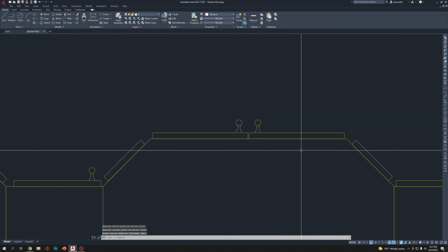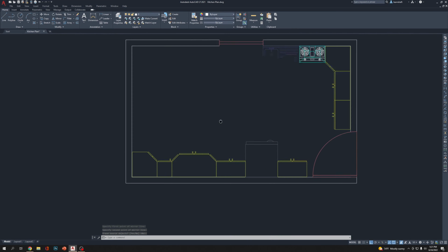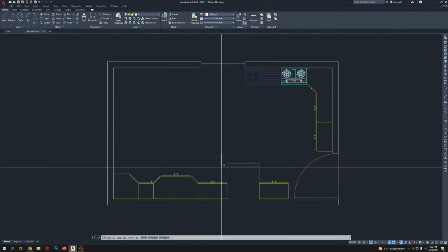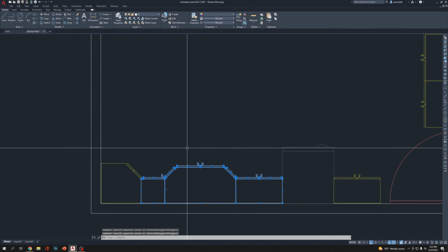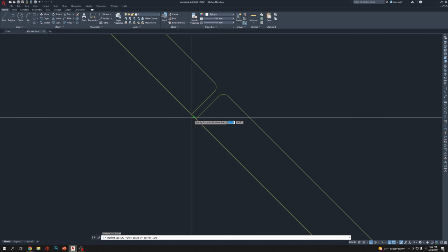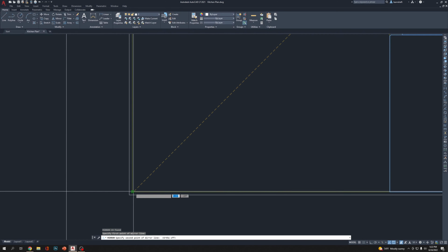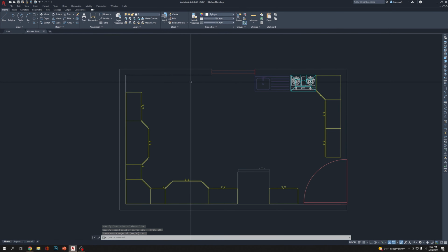I'm mirroring it to the other side, so this box is going to look like this. Yay! Okay, now I'm selecting this side and mirroring it to the other side. So I'm going to click on this corner, press F8, and go to this corner, click enter, and you see, yay, it sits perfectly.